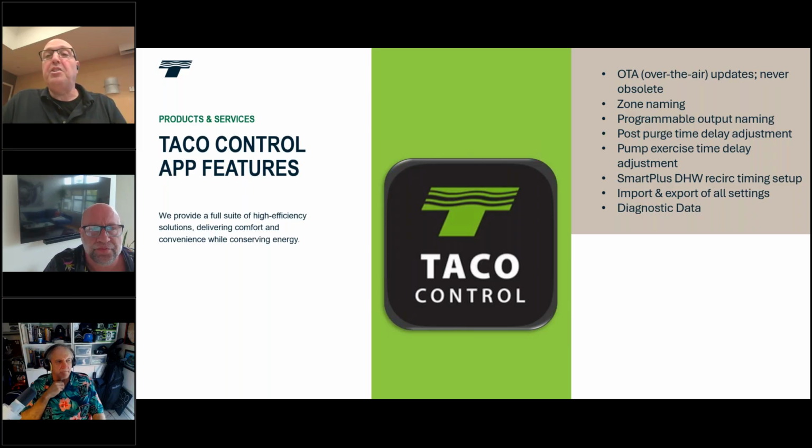Some of the simple things here, you can see we can name the zones, we can name outputs, we can change the post purge. We can actually change the settings in the smart plug. Right now, the smart plug by itself has 5 on, 10 off. We can change it down to 1 on and 60 off. So your choice, you can have some flexibility there. And we also can get some diagnostics out of it when you log in.